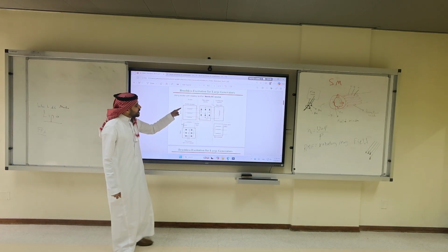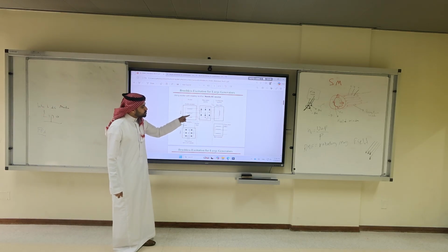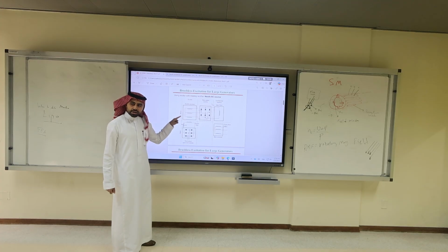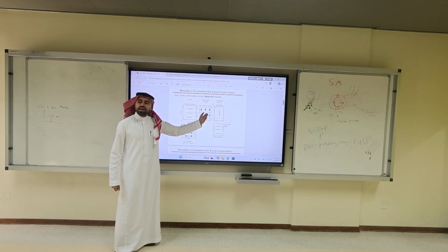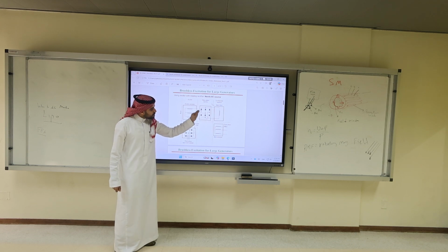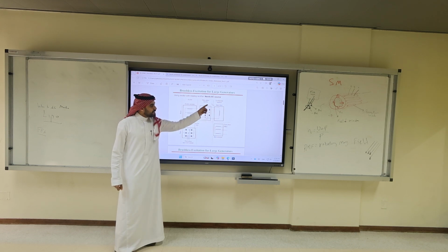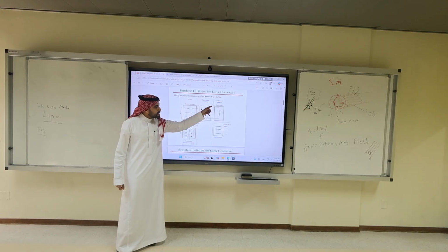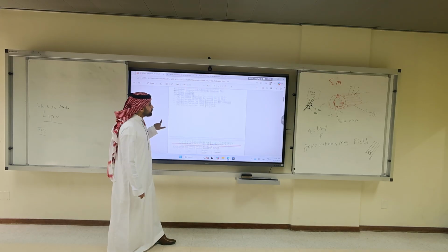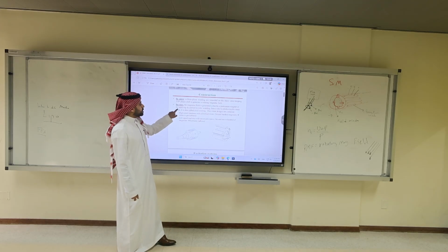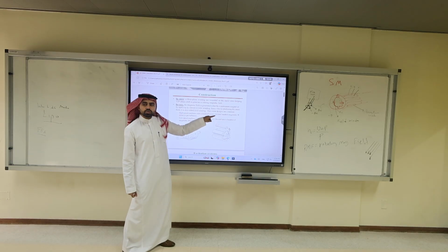You are going to have an induced voltage on the rotor windings. Apply them to what? A rectifier. When you apply them to a rectifier, you get what? DC. This is the field current DC. Then you apply it to the main field, the main windings. Then we satisfy the purpose of applying DC current to the rotor winding.